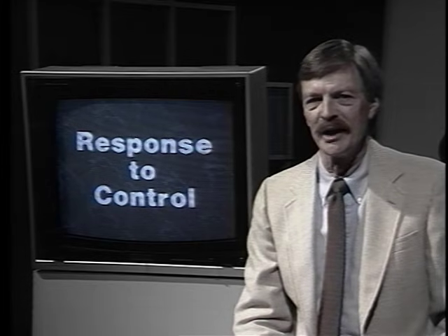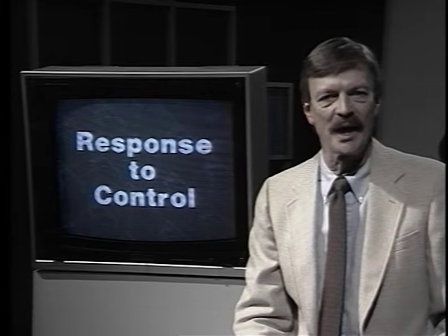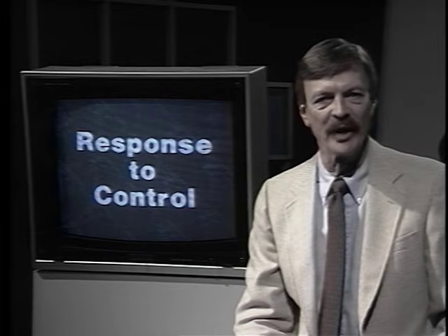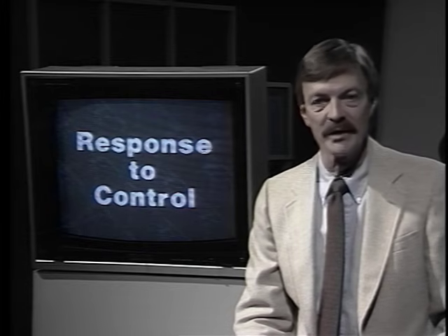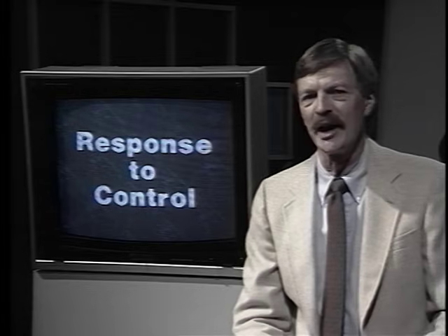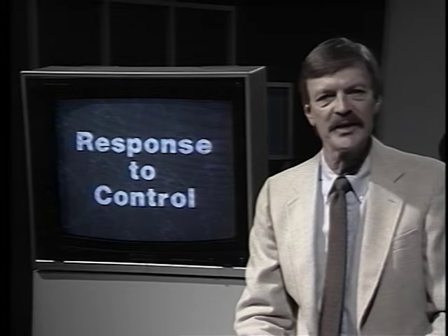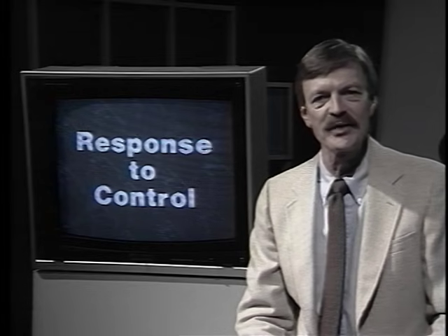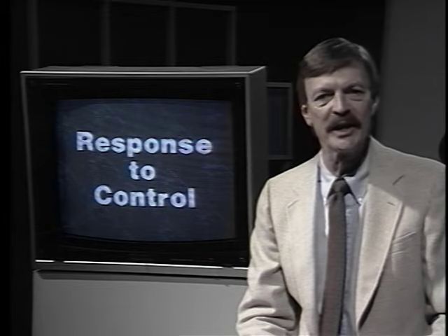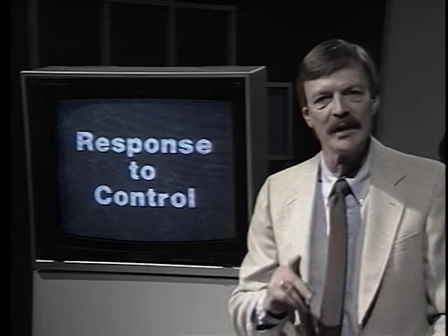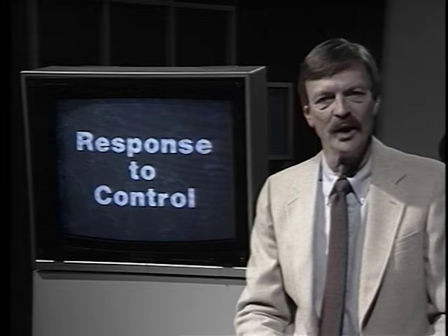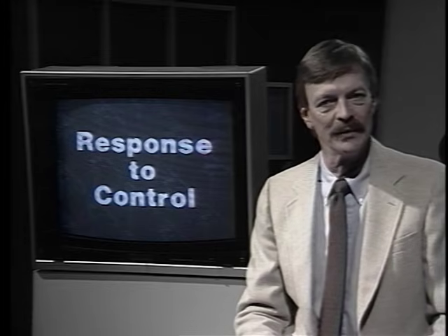Humidifiers are operated by controllers which are placed either in a space that is to be humidified or in the return air duct. A humidifier's response to control is gauged by the time it takes the unit to satisfy humidity demands. The key here is the state of the water when the humidifier is at idle.